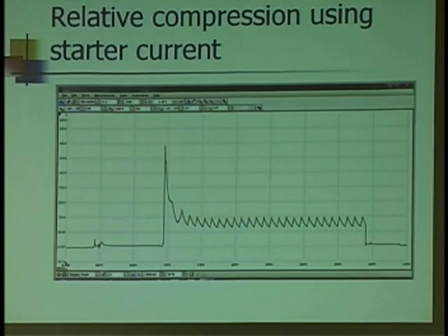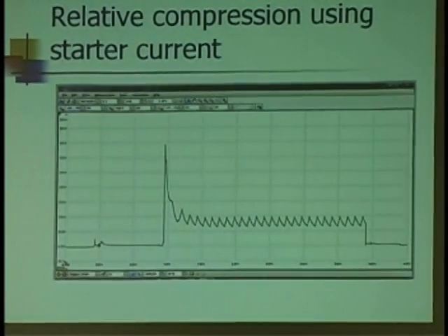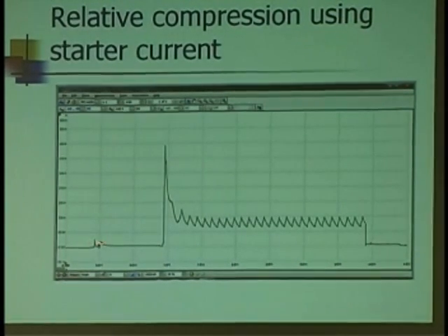Don't fall into that same trap. Don't try to memorize a certain pattern. Think about what's going on when you're looking at the pattern. I got the key turned on. I hit start. As soon as I hit start, the solenoid closes, the starter motor starts spinning. It takes a little bit to get that mass moving, but then finally it settles down and it starts cranking at a steady RPM.